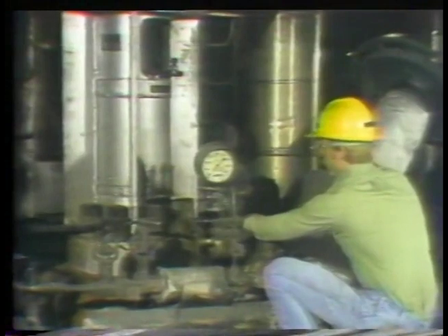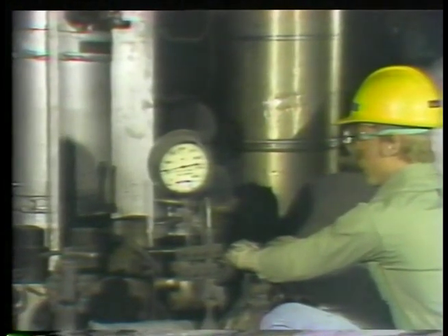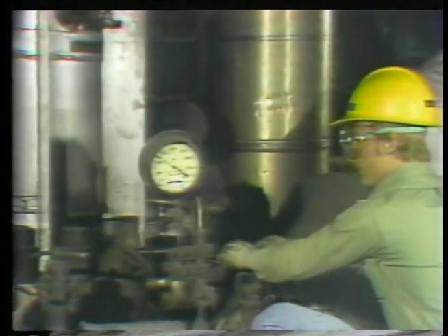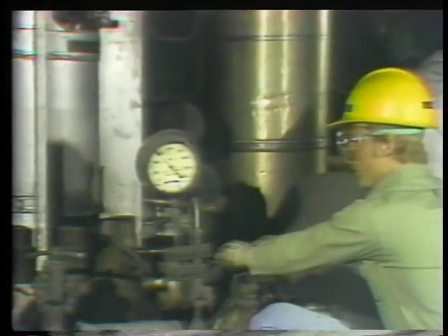So, if you are in this situation, make sure that you open gauge supply lines slowly so that sudden pressure exerted on the gauge does not damage its internal parts. If you should ever accidentally peg a gauge off scale, make sure you report it to the instrument department so that they can check it out and take any action that they deem necessary.